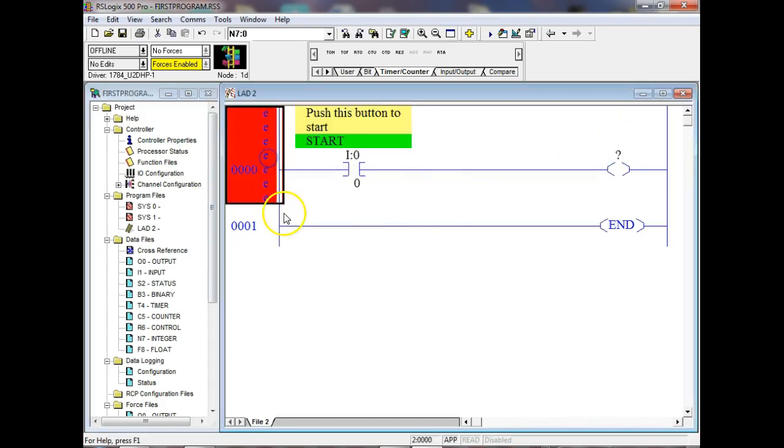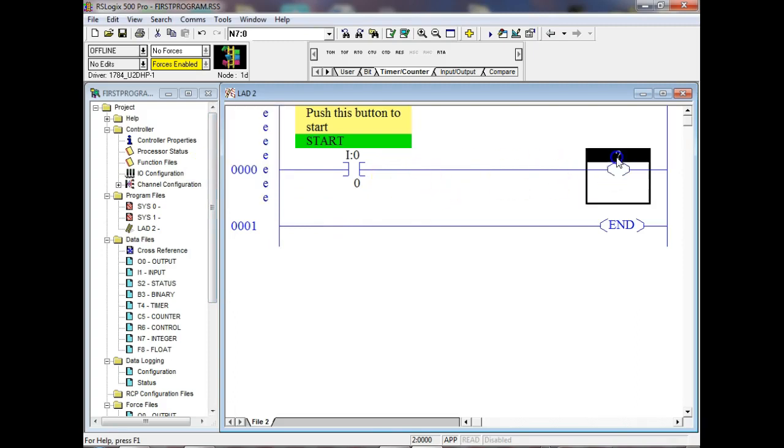We had one, when I first started teaching it, that was popping up on the 504s. It was faulting and faulting and faulting. And we couldn't figure out what it was. And Nancy said, well, there's no program in the PLC. So the PLC had been off so long, we don't have batteries in it, that it lost its program. So it's got to have a program in there. So all we do is just download a dummy program in there and get it going. So sometimes the errors are hard to figure out.